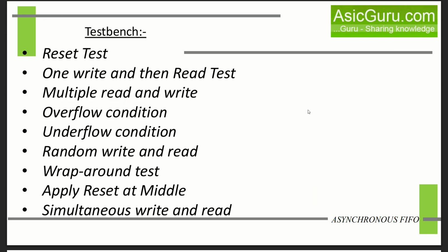Now let's see the different test plans to validate our Asynchronous FIFO. For that, I use 9 test plans: reset test, one write and read test, multiple read write test, overflow condition, underflow condition, random write and read, wraparound test, apply reset in the middle, simultaneous write and read.